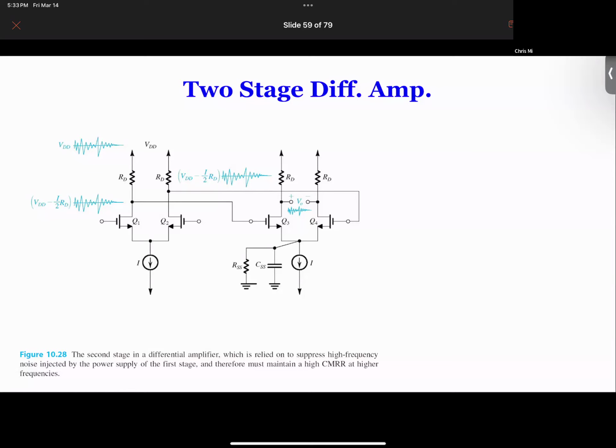And if you recall from the previous slide, we had this gain in the middle band, and we have this CMRR start to drop, which is not good. But when you take the same signal and amplify this output in a second stage, what happens? The middle band is going to be good, but the common mode rejection is getting even worse, right?